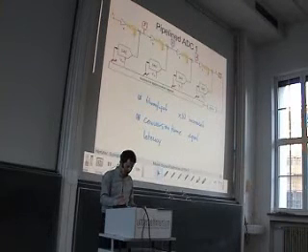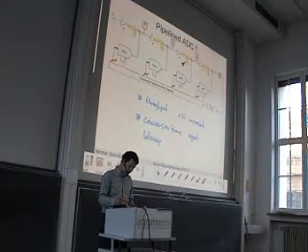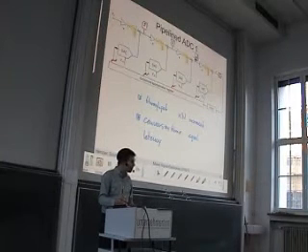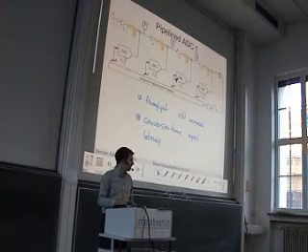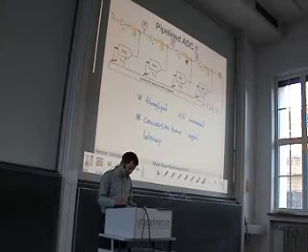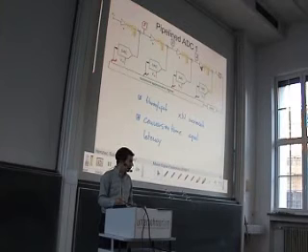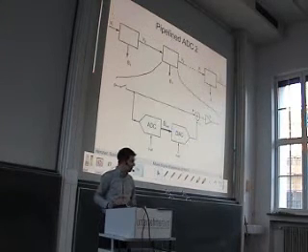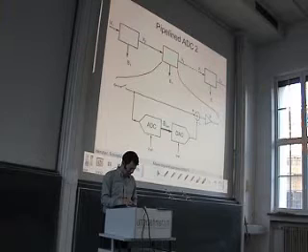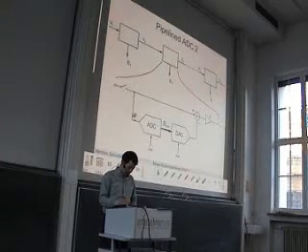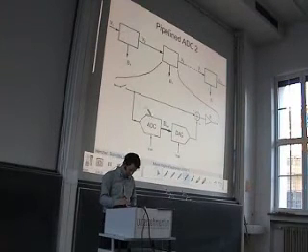So let's start here. For each element, we have a sampling element. We have a quantizer. The quantizer checks is it positive or negative, and depending on the result, we steer this DAC. Then we subtract the sampled signal from the DAC signal and amplify the remainder by a factor of 2. And what you can see here is exactly the same, only that it is in a somehow generalized form. We sample the input signal here. This, what is called here ADC, is the quantizer. So this is the quantizer.